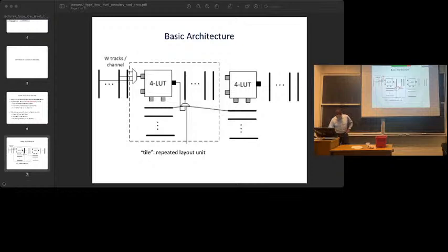So you're saying, what if the output could also control these? People have actually proposed that. So if you want, for your term paper, you could go look at that. People have said, hey, multiplexers occur all the time in designs. So they actually turn out to be a significant fraction of the typical design's logic. And we have all of these routing multiplexers. Couldn't I use those to implement the end user's application? So people have actually tried that. The basic problem is it's really hard to route.